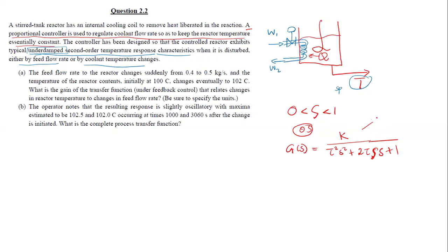And then here at the top, we are looking at the gain. So if you do remember, the gain is actually defined by the change in the output divided by the change in the input into our system. In simple terms, we can even just look from the diagram. Our input will be the flow rate, and then our output is going to be our temperature, our process variable. So the ratio of output and input is given by the gain, which is denoted by the letter K.